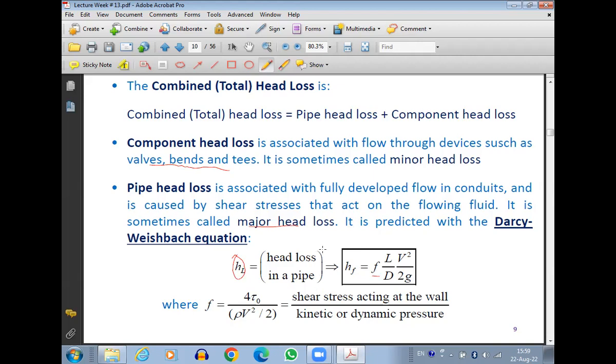Okay, so you have a pipe which is made up of plastic, a smooth pipe, and you have a pipe made up of concrete. Even if you make the concrete as smooth as you can, the surface will still be very rough. So the losses of energy as the fluid flows through the concrete pipe will be more than the losses of energy as the fluid flows through a plastic pipe. Suppose it is a very smooth pipe, let's say a glass pipe. In case of the glass pipe, it is very, very smooth, so the losses will be much less.